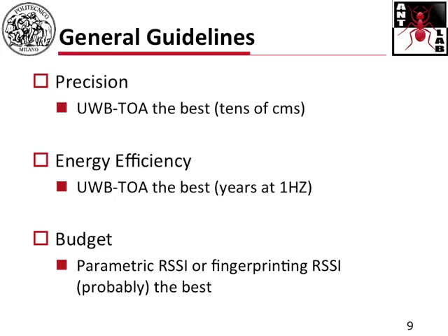Okay? So to summarize, if your target performance measure is accuracy or precision, you'd better go for systems based on time of arrival kind of localization approaches, where again you estimate the distance based on the difference in time between when the signal was transmitted and when the signal is received, and this delta in time gives you an estimate of the distance between transmitter and receiver. And generally, these kinds of systems are based on ultra-wideband, which is a specific technology used for communication.